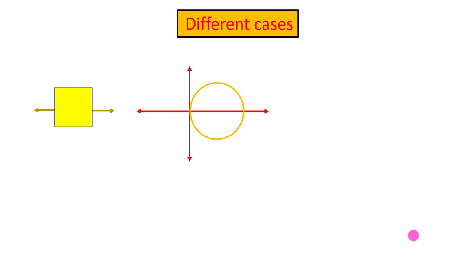So the first thing is, suppose I take a uniaxial case. For uniaxial cases, how is the plane stress going, and how is the Mohr circle going to look? First thing is that if we look at this face, it's going to give us some sigma value and tau is 0. It means that this point is going to lie somewhere on this horizontal axis. Now for this face, sigma is equal to 0 and tau is equal to 0. It means that it's going to lie on the origin.